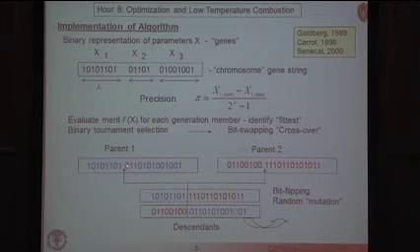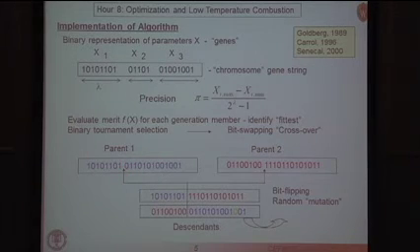And you perform what's called bit swapping or crossover after performing some selection procedure. So for example, at a random place in this gene string, you cut the gene, and you simply move this over and give it to the parent. So basically you create new designs from those good performing parents.